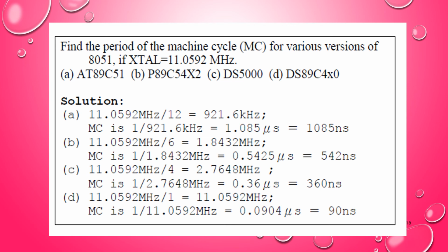So to summarize, in this whole session, we have discussed in the beginning about jump instructions. There are mainly jump instructions associated with accumulator conditions and flag conditions. We have seen a number of jump instructions like JZ if accumulator is 0, JNZ if accumulator is not equal to 0, DJNZ decrement and jump if register contents are not 0, CJNE compare and jump if not equal to, accumulator with data, and CJNE register comma immediate data, compare register content with immediate data, and if not equal, then also you can jump.